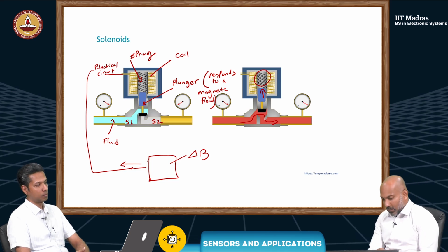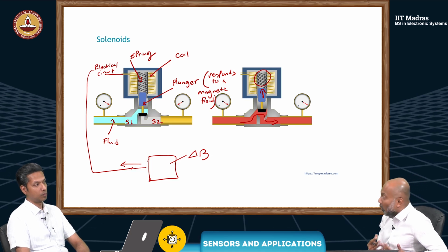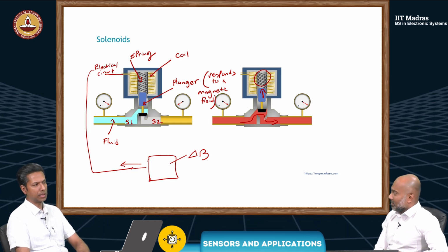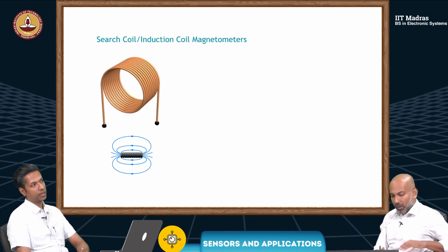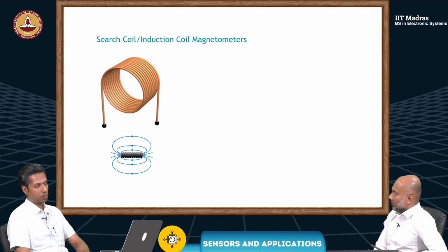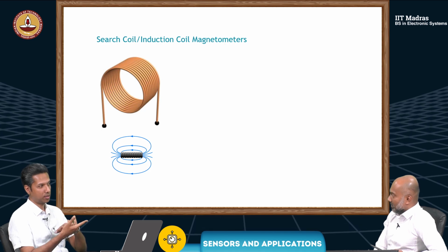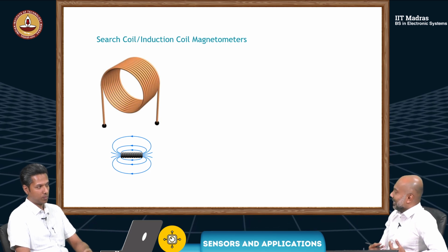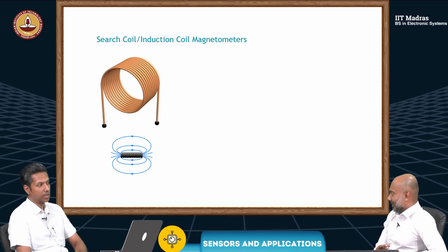So my question is, we've done Maxwell's equations. Can we use the same coil? Here we are giving the current, but can we use the same coil as a sensor? Yes. Is it possible? I think the inductance of the coil will change depending on the position of the plunger. Suppose you want to sense the position, it could be a way. Exactly. If you want to detect something, the same coil, technically, according to the equations we studied yesterday, can be used.